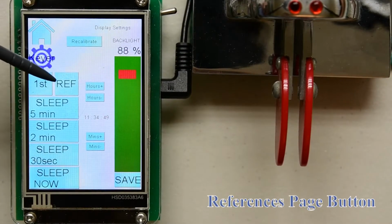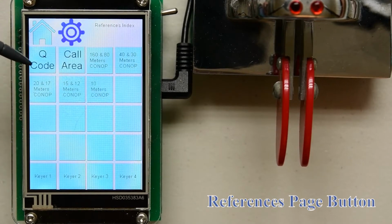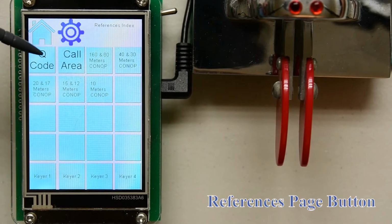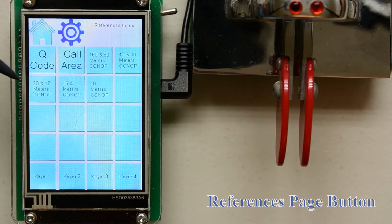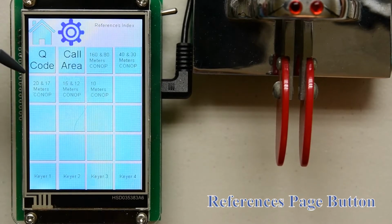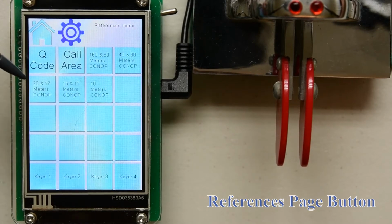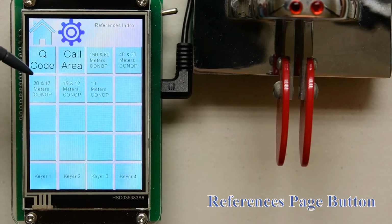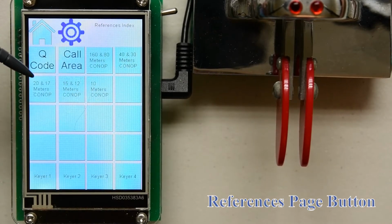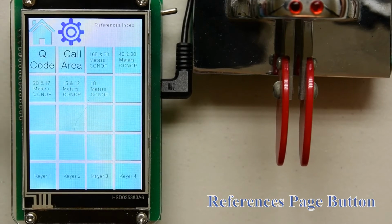The reference key here on settings, there's also a reference key on home, sends you to a page where you can have referenced different pages of short text information. The framework allows for 20 pages. You can use the Nextion IDE to add or modify pages. There is in Nextion a hard limit of 250 components allowed per page and 254 pages per project. So you could have multiple pages of reference if you wanted.